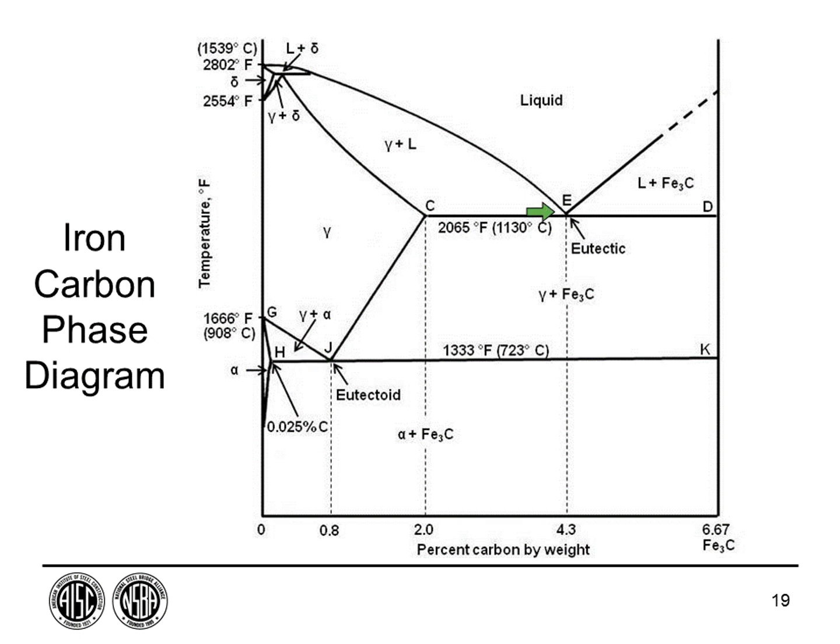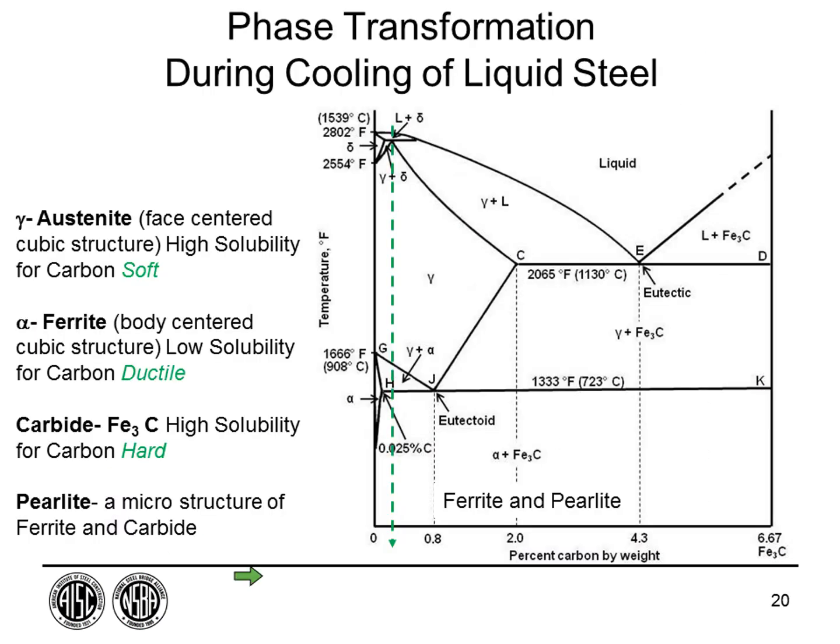To give you an idea of what a eutectic point is, if you've ever soldered an electrical connection with 60-40 tin solder, you'll notice when you're soldering, it's a liquid, and then when it cools, it immediately turns to a solid. That means it's going right from here down to here. That's what would happen with the steel out here, but this is way too high of carbon. We're typically over in this range where I've shown this green line.